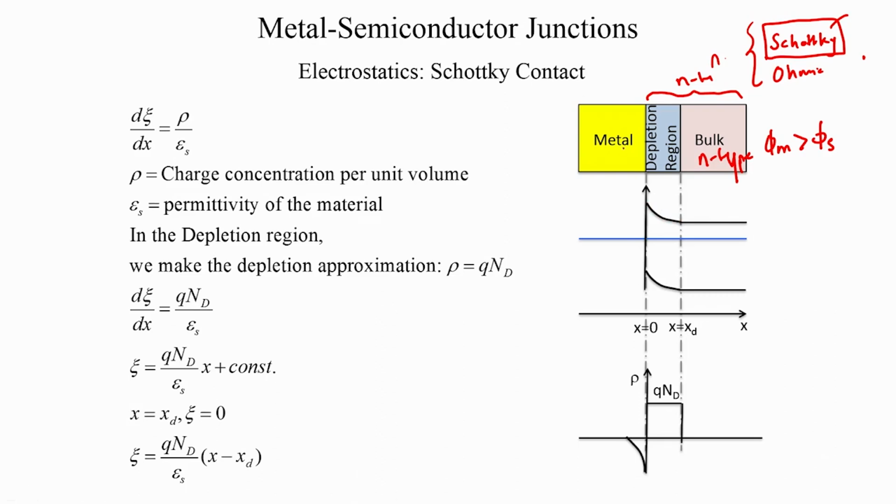If you think of this region, we already discussed that the electrons are not encouraged to exist here because this region has given up some electrons to the metal, and it has resulted in the bands bending in this particular manner, which encourages electrons to roll downhill and keep away from this region.